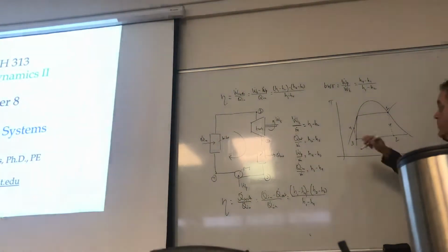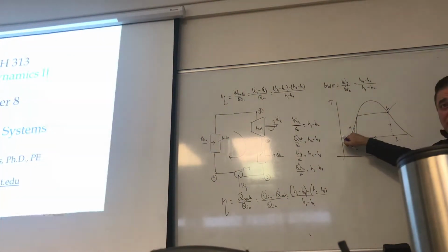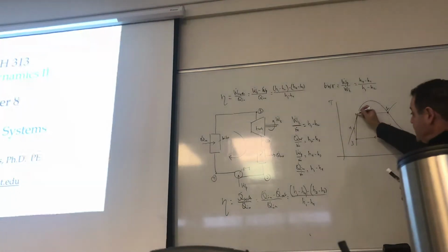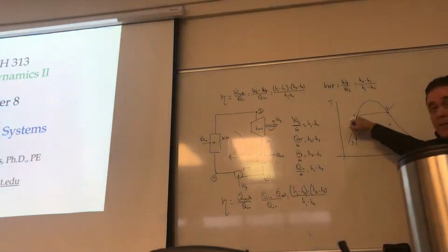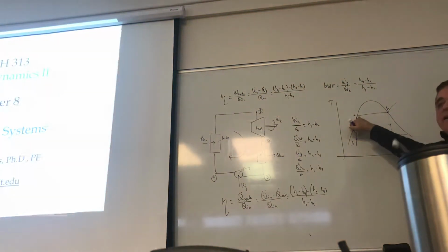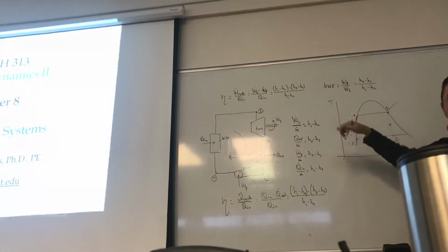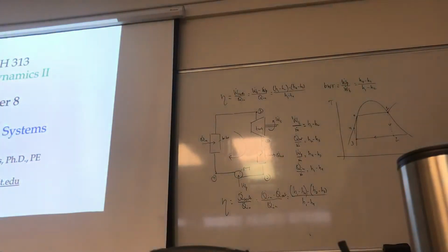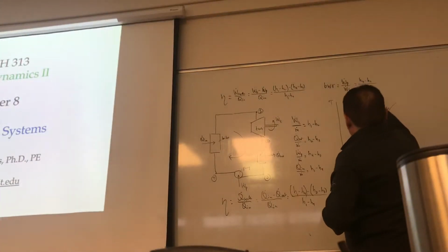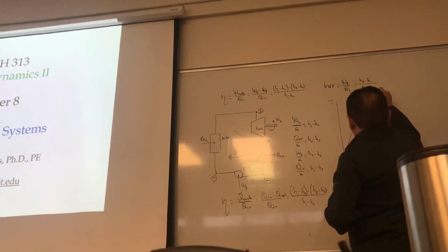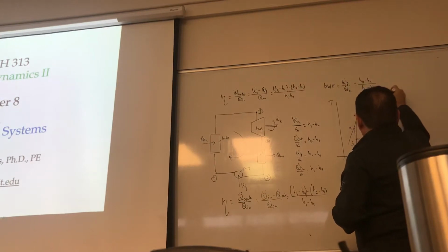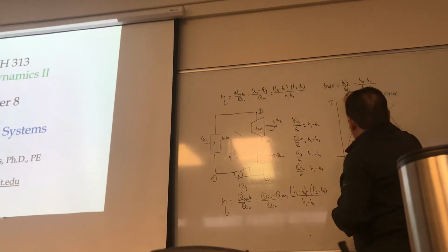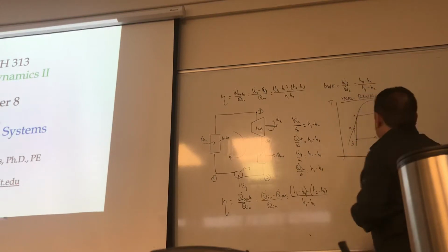Here you have compressed liquid, and you keep adding heat until it becomes saturated liquid. As you keep adding heat, the temperature does not change because you have a change in phase. So this is the good old ideal Rankine cycle.